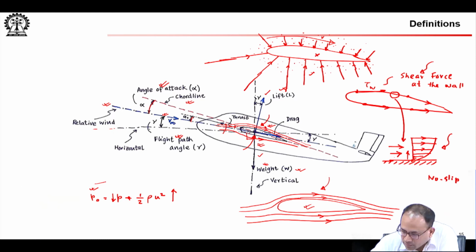So, it goes from 0 velocity. So, you can think of these horizontal line magnitudes as the magnitude of velocity, and eventually you reach u infinity magnitude asymptotically. Okay. So, it takes forever, but what we do is we say that the distance that is required to reach about 95% of u infinity. In some texts I also see 99%, but nonetheless it is just a convention.